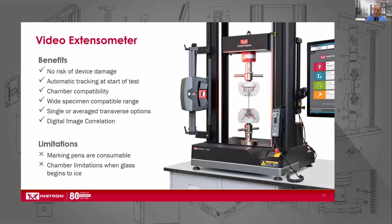One limitation that I do want to expand on is testing in a chamber. So this isn't exactly a limitation of the AVE, it's really an application limitation. In extreme subambient temperatures, ice will begin to form on your chamber window. If you've ever gotten in the car on a very cold day and had ice on your windshield, you need to defrost your windshield before you start driving so you can see. Video extensometers need to see like us to function.